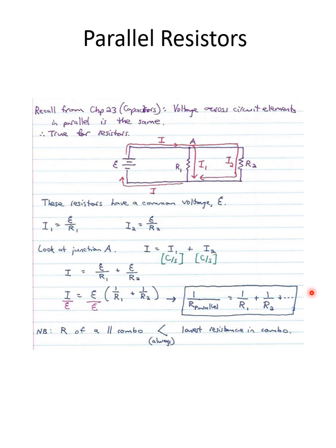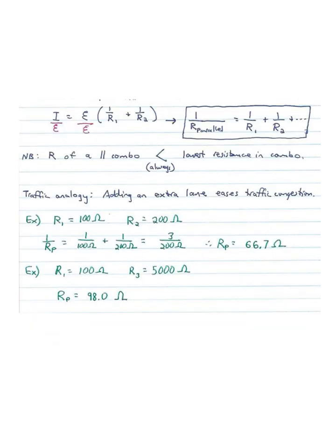We don't have anything as low as 20. We can actually add the 100 ohm resistors in parallel so that it will overall come out to a smaller resistance. In fact, 5 of them in parallel will make a 20 ohm resistor.